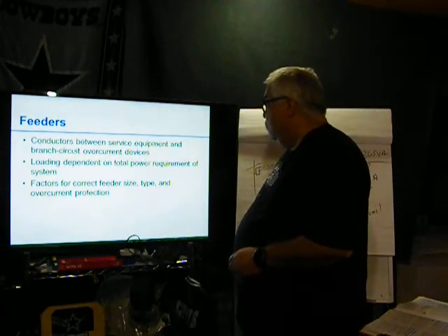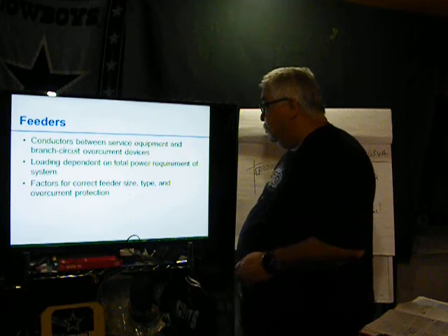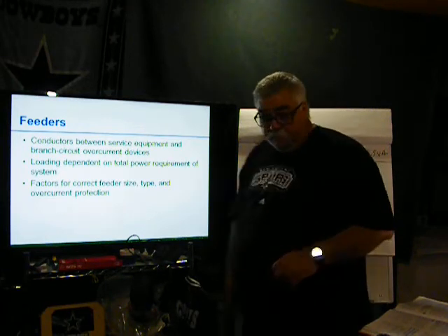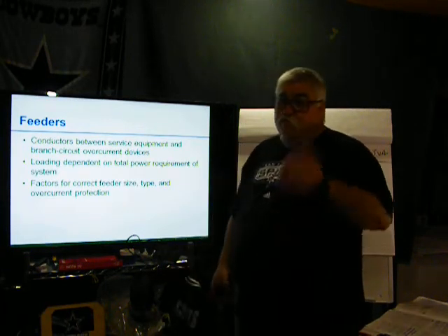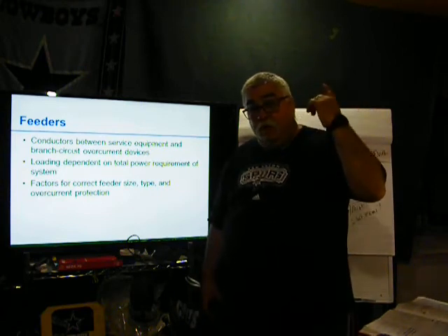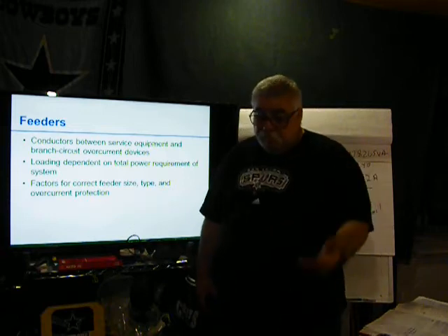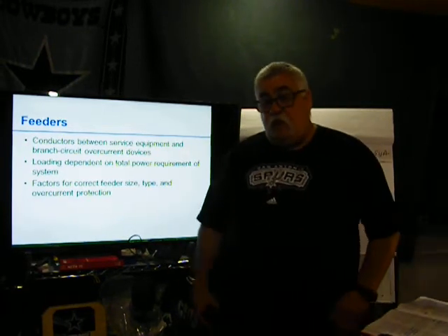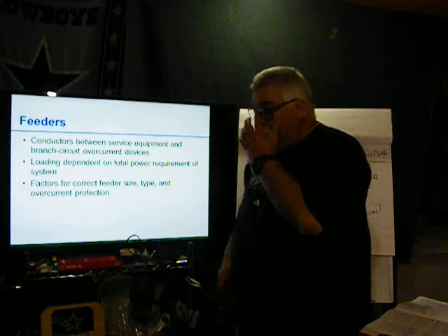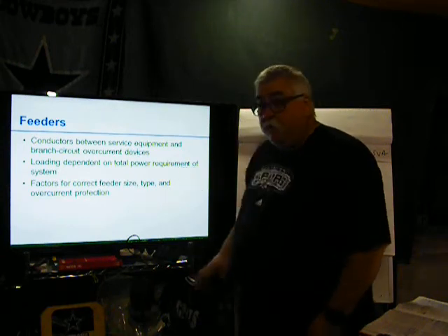Load dependent on total power requirements of the system. Okay. So what does the system require? What's being plugged in? Lighting, power, motors, air heating, air conditioning, water heater, whatever else they got. Whatever is being plugged in is your total power requirement.